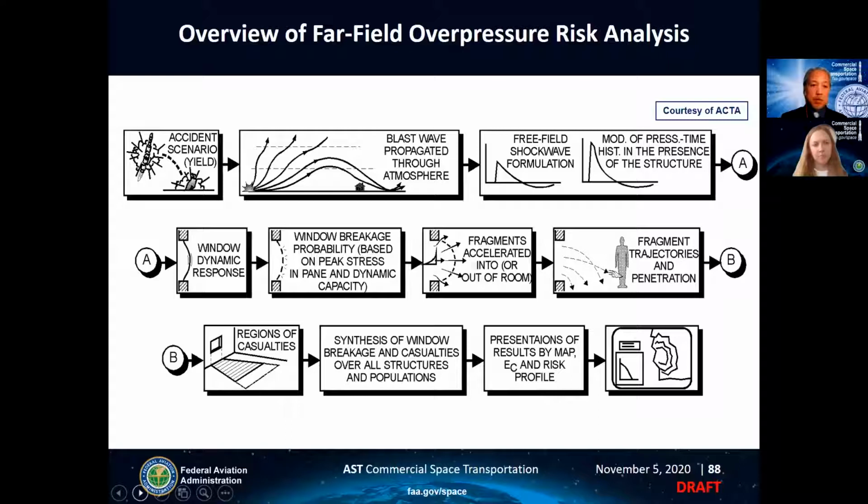Such an event happened in San Antonio, Texas in the early 1960s. It's kind of the quintessential event for this phenomenon, called the Medina event, where a munitions depot exploded. 110,000 pounds approximately was the equivalent TNT yield, and that resulted in over 3,000 windows reported broken in downtown San Antonio, whereas there were areas in between the explosion site and where those windows were broken, where there was in fact no damage.